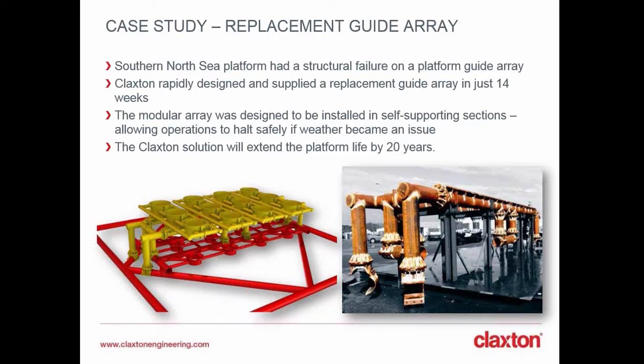One of the main challenges for this particular design was that it had to be installed with rope access personnel. So the design was modular, but because it was being carried out by rope access personnel, each section had to be self-supported in case the rope access operations were interrupted by adverse weather conditions or anything else. So you just have to make sure that once you install a segment, if you had to leave it there for a day, it will still be in place when you come back to finalize the full installation of the guide area.